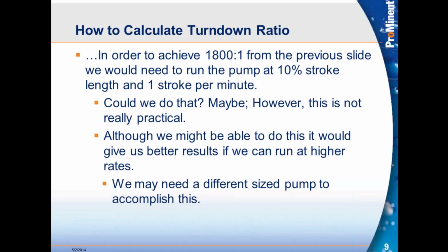One stroke, 1 minute time, an entire minute of flow goes past. Now the pump doses again. It doses that 1 ounce of chemical in. We've met that ratio that we needed to provide. We've done our job. We are right where we need to be.